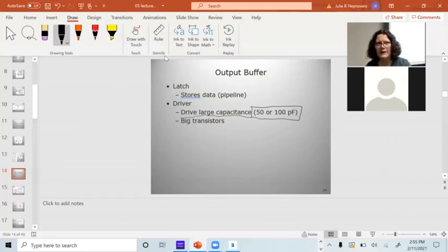You're going to have the possibility of disaster when somebody comes along with a scope probe and accidentally shorts 2 pins together. You could potentially short this out. Somebody could stick the chip in their pocket and carry it across campus. Sorry, Taylor. And do some ESD damage to it. A lot of things can go on with this chip.